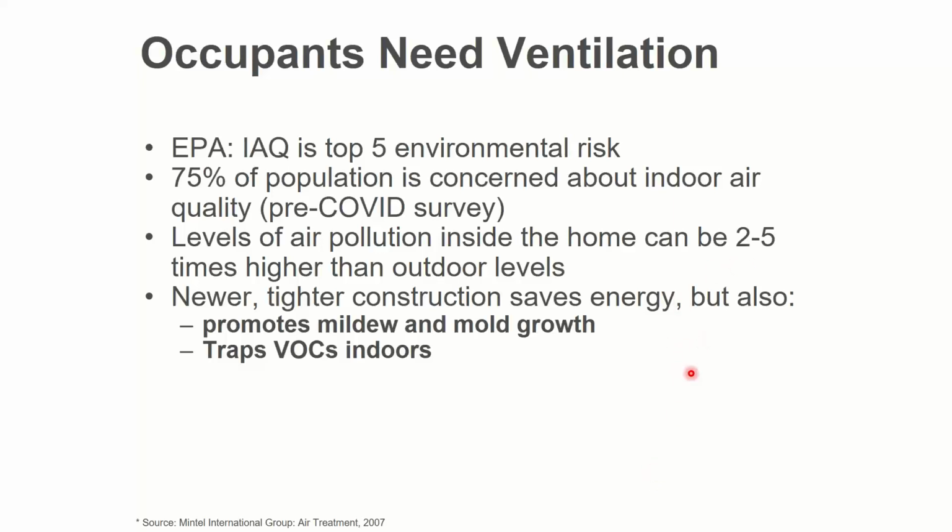As buildings get tighter and tighter, it becomes more and more critical that we have mechanical ventilation systems. If it's an old, crappy, leaky building, you're accidentally ventilating it through the leakage. But as you tighten up old buildings, or as you build new buildings which are inherently tight, that becomes more problematic, both from a humidity control standpoint and as well as trapping all the VOCs from the furnishings in the building. So we got to pay more attention to that.